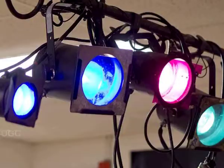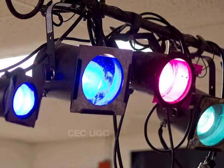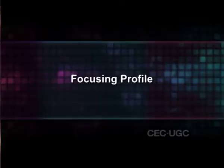The way light fills a beam can also be altered, and this is called flat field or peak respectively. Flat field means that the light is spread evenly throughout the beam. Peak means that a larger amount of light is concentrated in the center of the beam. Some profiles are designed to provide a beam of variable size. These luminaires have two lenses which can move independently of each other. One lens is used to vary the size of the beam, the other lens adjusts the focus.